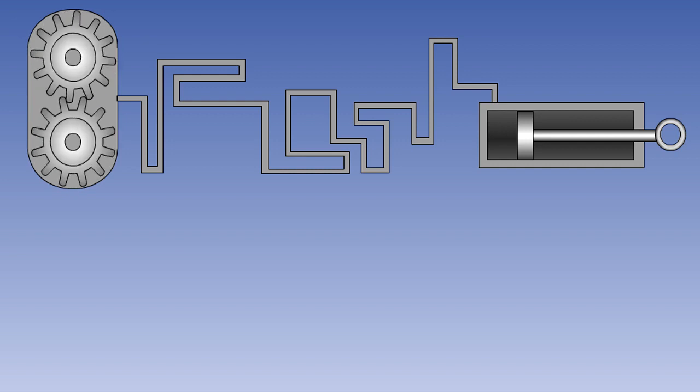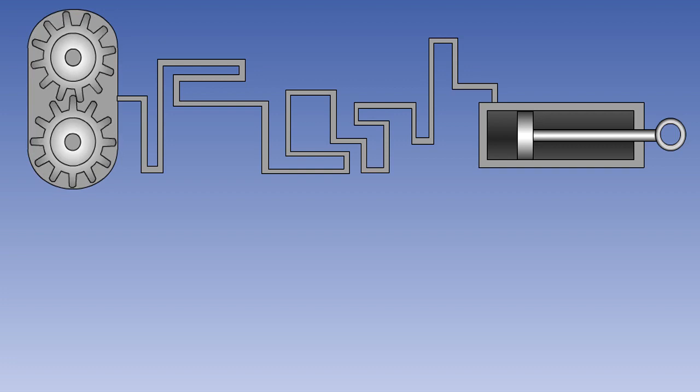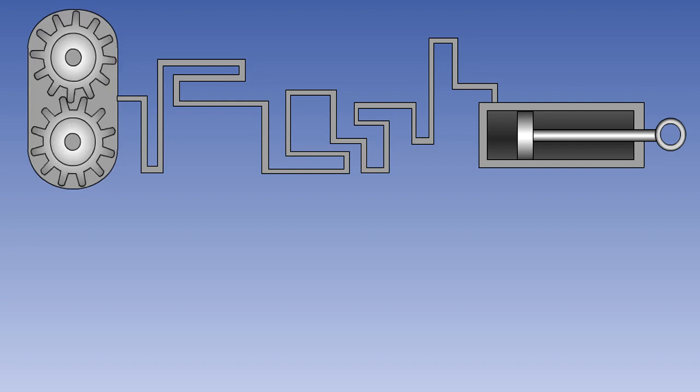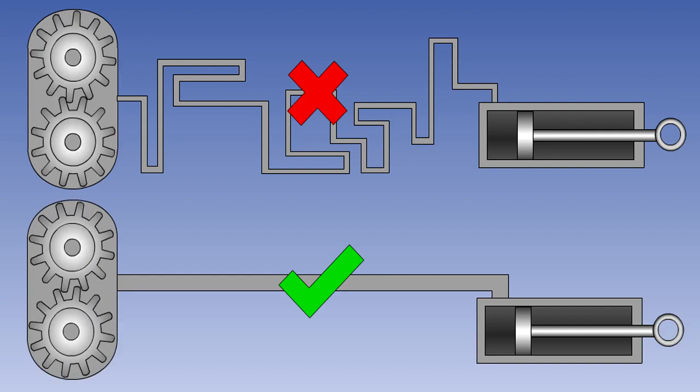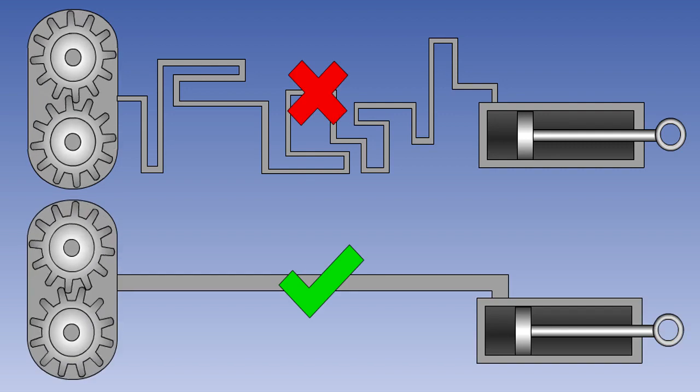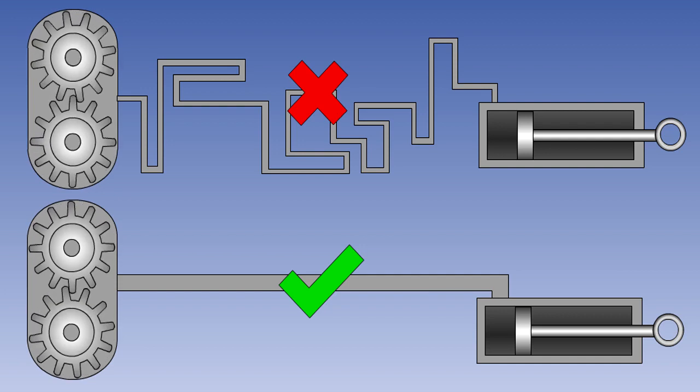Friction between pistons and cylinders, and piston rods and bearings, cannot be completely eliminated. It can only be lessened by good design and workmanship. The friction between the walls of the pipes and the fluid depends upon the velocity of the fluid in the pipes, the length, bore and the internal finish of the pipes, and the number of bends. Good systems are designed with pipe runs being as short, wide and straight as is practicable.